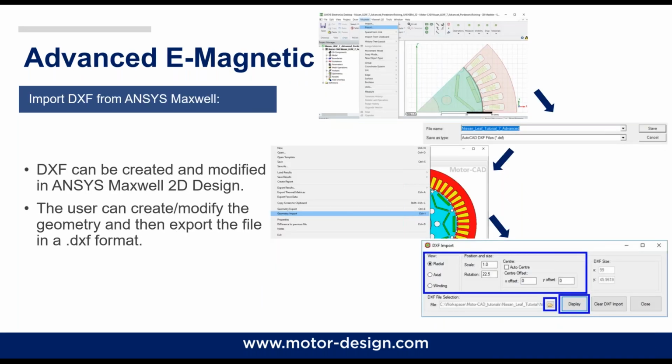Another important feature in MotorCAD is the import of DXF geometries, which gives a very fast estimation of the electromagnetic performance with sufficient accuracy. DXF can be created and modified in ANSYS Maxwell. So once the user is happy with the design in ANSYS Maxwell, it's possible to save the model in DXF format and then import it in MotorCAD. There are several DXF import options for the electromagnetic module. For example, single slot and pole, single rotor pole, single stator slot, entire stator and rotor, entire rotor, and entire stator.